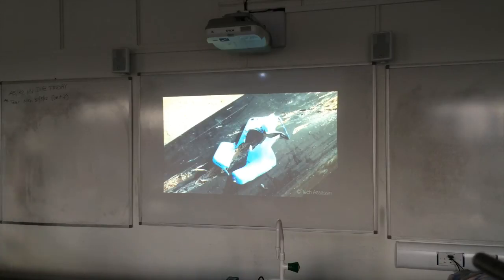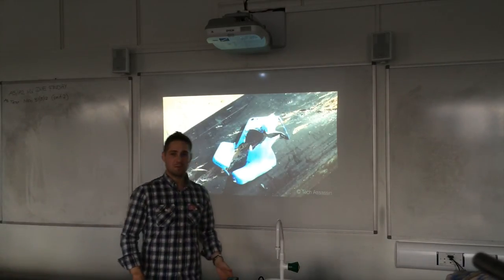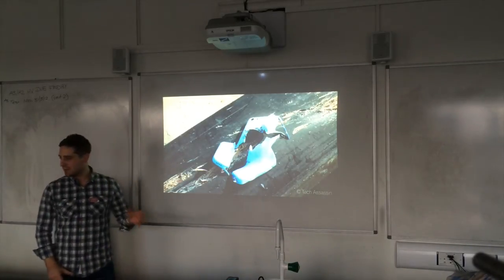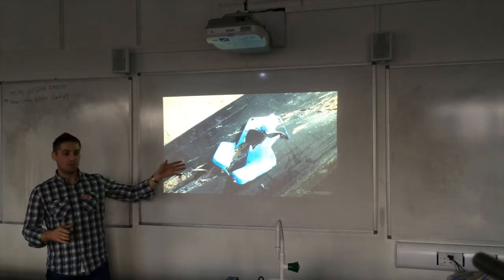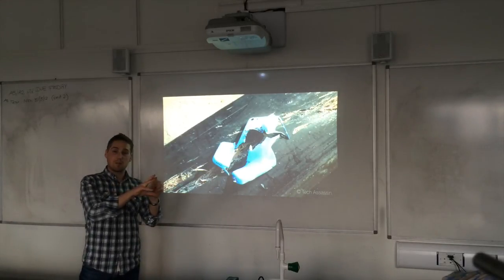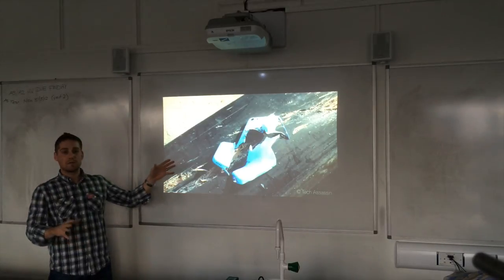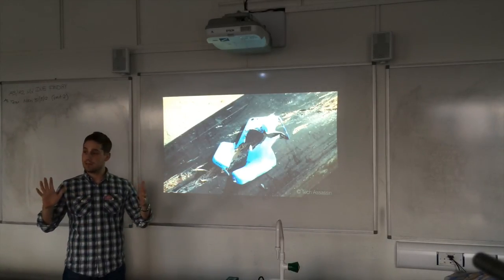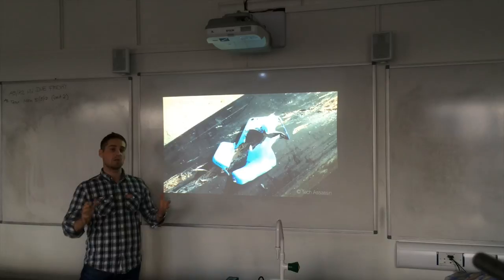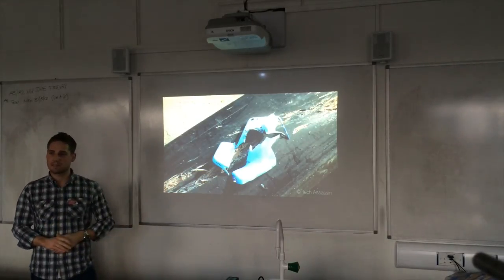So, high pressure, it's a bullet from a 50 cal rifle, a Barrett 50 cal. Incredibly large force exerted on a small area, causing incredibly high stresses. Now, even if it wasn't a bullet hitting it, if it's something larger and exerting the force over a larger area, sure it'd smash it, but you wouldn't get anything quite as dramatic as that.